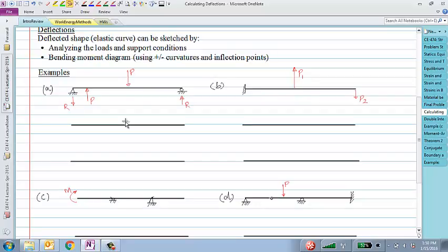Why does it not change? What equation are we using to find the reactions? Right, sum of forces and sum of moments. So clearly these two forces put together with some specified distance between them, as long as the distance between them doesn't change, the reactions won't change, right? Because the length of the beam is constant, so that would indeed be the reactions. Now, knowing that these are the reactions, what would be the shear force diagram?